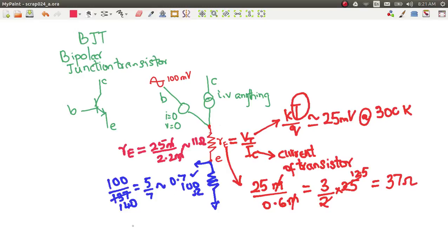So if you look at this resistor ratio, it's the same 100 ohms, which is the bottom resistor, divided by something like 111 ohms, or even 110 ohms would have given me, which is around 90%, right? It's not equal to, but it's approximately equal to 90%. So this should give me around 0.9 volts, which is what we see in the result, which is around 88 is what we got in our measurement.